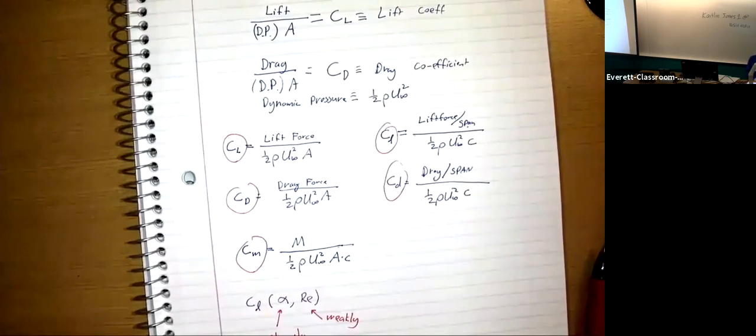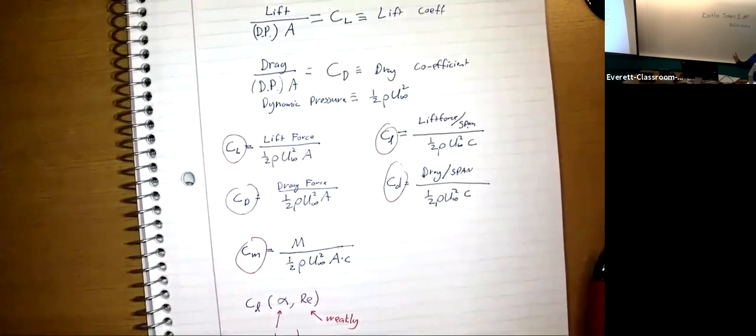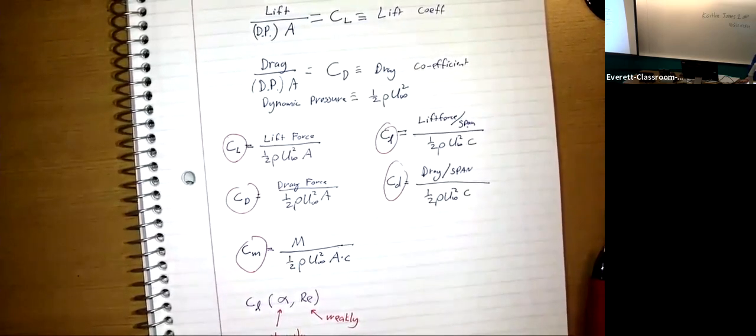If we assume that there's no boundary layer on the airfoil, we get what's called inviscid flow theory, and we can come up with an approximation of what the lift and drag forces are at given wind speeds. But that assumes there is no boundary layer around the wing. Oh, but it turns out there is. How big that boundary layer is depends not just on the shape of the wing, but also on the roughness of the surface of the wing. And so little imperfections on the wing can change that.